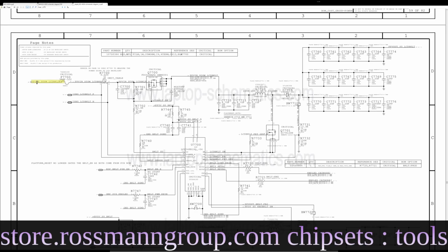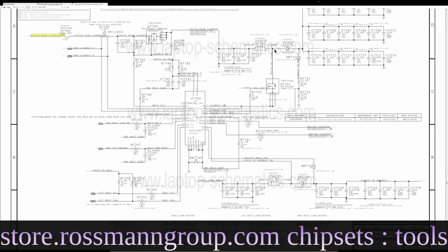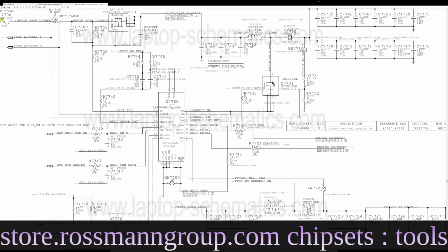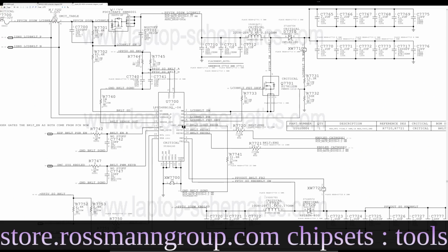If you wonder how I know that that's 12 volts when it says PP, Vin, SO, Sys, whatever, it's in page 66. Now that is going to go through here, and this is a coil. This transistor here is going to short the voltage from the coil to ground. So this backlight driver, this chip, which, hint, is most likely this, is going to do that.